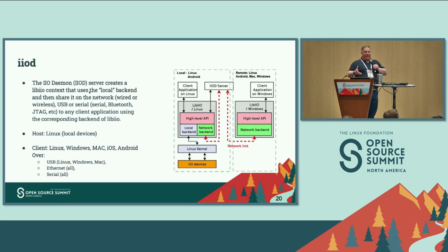So that's where IIOD comes into play. This is part of the user space library. We have a daemon that serves things up over a variety of different transports, like I talked about before, whether that's USB or Ethernet or serial, to abstract that communications piece.